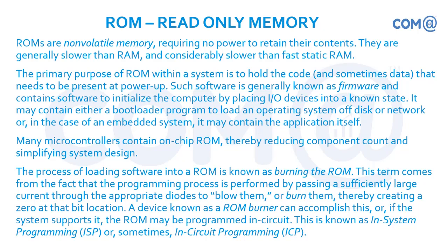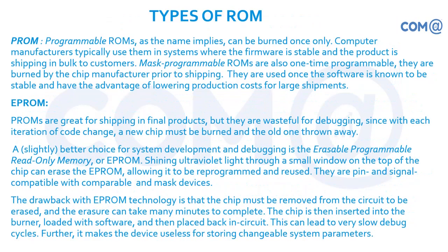So we'll define what program is required and verify it. Later we'll upload the data or burn the program to the chip. So this is the ROM, read-only memory. Because of this, it is also known as in-system programming, or sometimes in-circuit programming, ISP or ICP. PROM, programmable read-only memory, unlike ROM, is a one-time access.